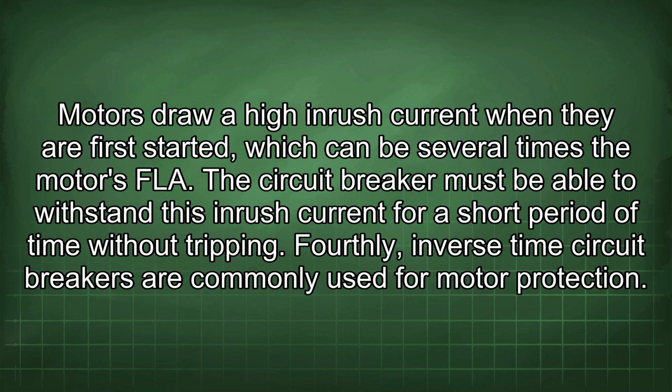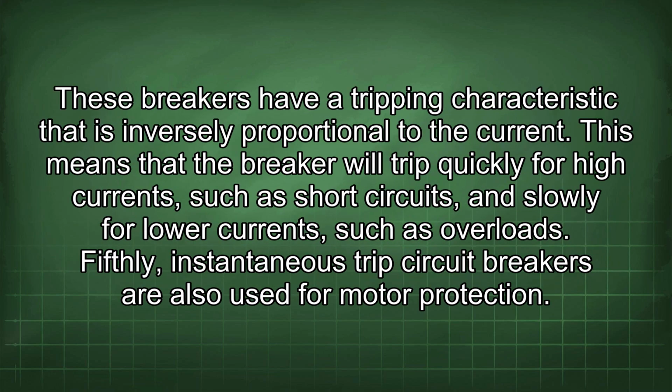Fourthly, inverse time circuit breakers are commonly used for motor protection. These breakers have a tripping characteristic that is inversely proportional to the current. This means that the breaker will trip quickly for high currents such as short circuits, and slowly for lower currents